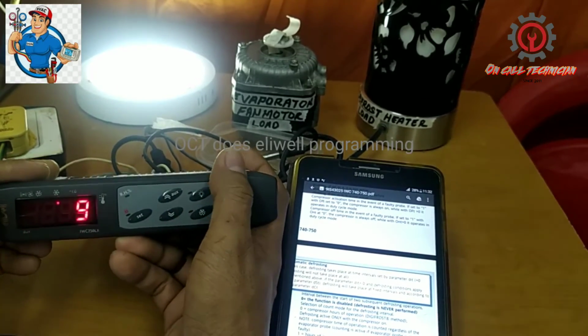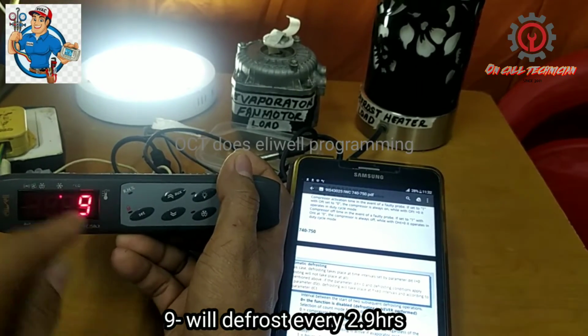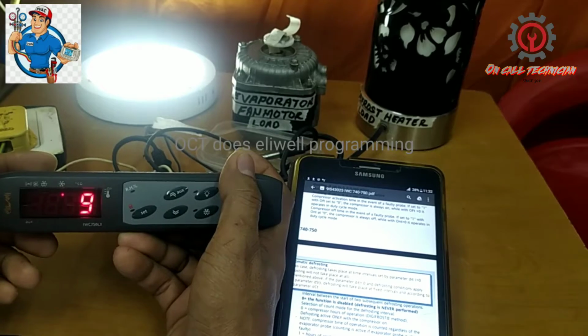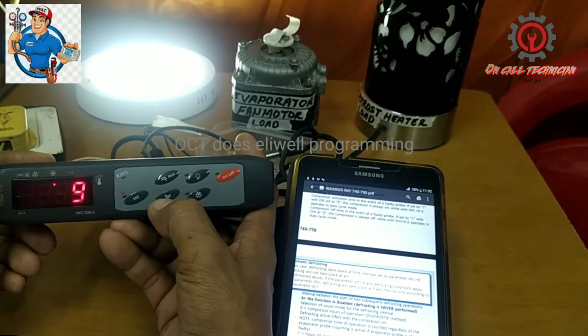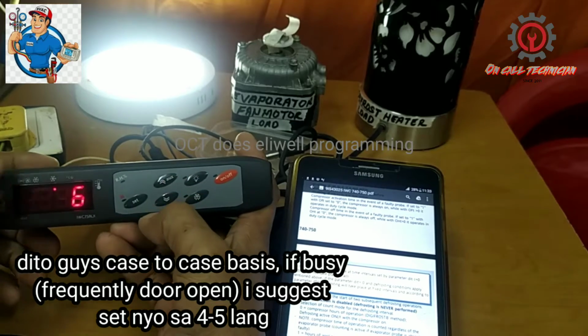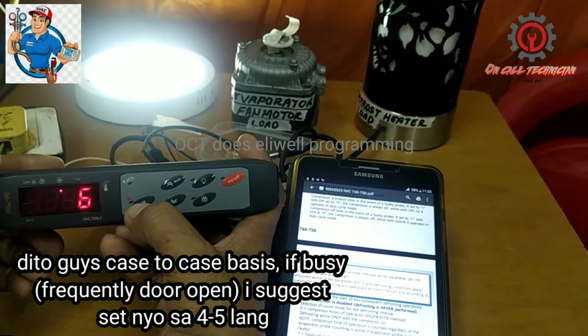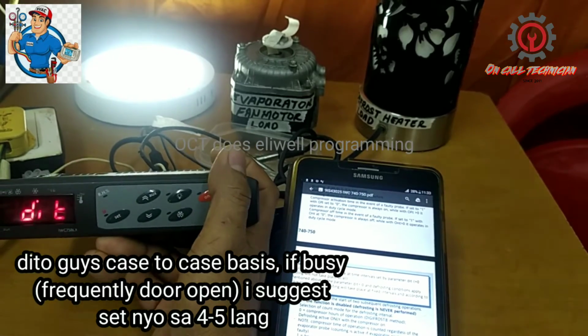And if you put it to 9, every 2.6 hours, the electrical or the hot gas will engage. So if you want to set it to 7, it's up to you. If you want 6, it's up to you.